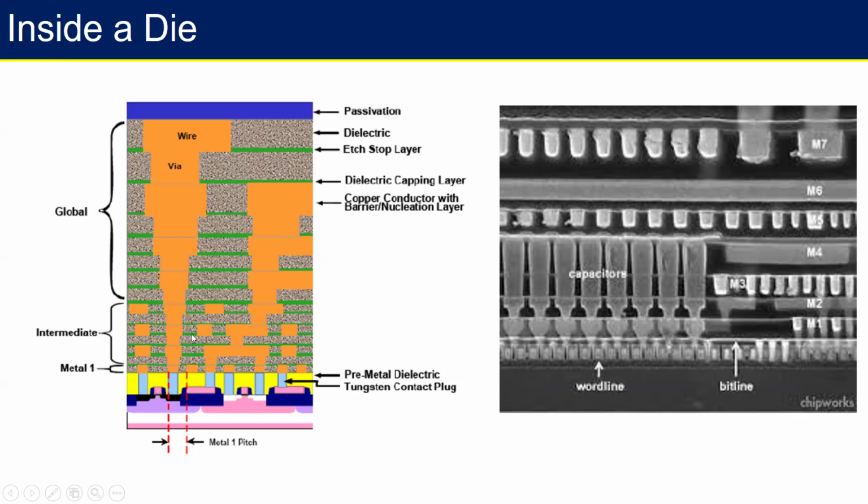And then you see that you are putting dielectric, metal, dielectric, metal, dielectric, metal on top of each other to reach the end of the chip, right? And as of now, in the dies made with the recent nodes, we typically have around 10 to 12 or 13 even. And it has been increasing from the time I started my career. I saw maybe 4, 5 when we were starting, then 7, 8, then it started increasing again: 10, 12, 13, 14.